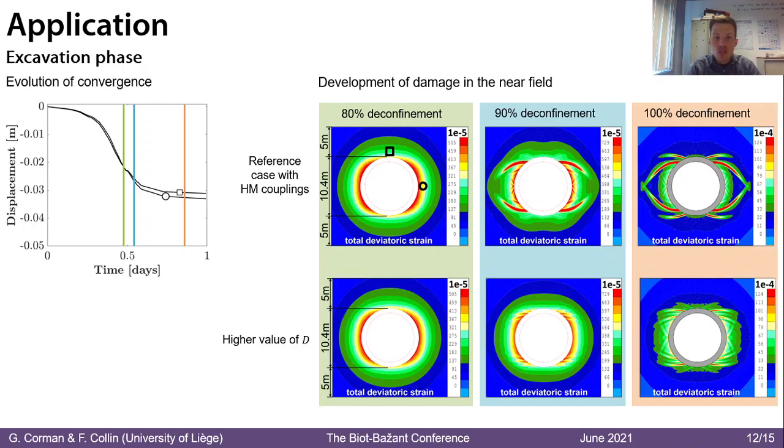The role of the second gradient elastic modulus D in the proper representation of the shear bands and in the control of the bandwidth can be highlighted by considering a value 10 times higher for this specific parameter. It follows that considering a higher internal length scale for the model tends to homogenize the development of the shear bands, attenuating in this way the initiation of local intense bands in the present case.